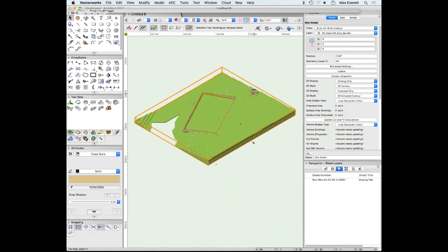Sometimes, did you go into top plan view before? Because if you don't go into top plan view, I found that it skips over. But if you do it when you're in the 3D view and you paste it, it doesn't work. So you want to be in top plan. If you're ungrouping and trying to get the site model out of the 3D symbol, do it in top plan, to be safe. It could be that. Okay.